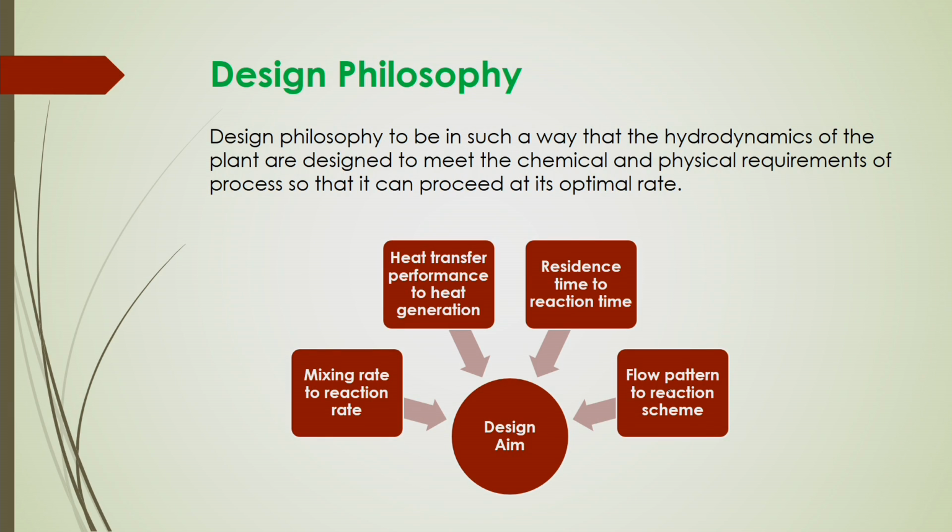So, based on that dispersion number, you have to assess whether this degree of mixing is enough or not. It will give you the ideality or non-ideality of that reactor. So, the flow pattern, how the fluid will be mixed, and also the fluid element. If particles are being used, what will be the flow pattern of those particles, what will be the distribution of the particles inside the reactor, that should be considered. All these things are considered as hydrodynamics.